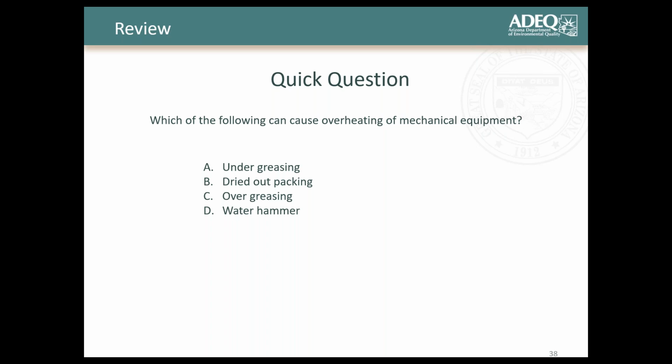Yeah. And this is a great question too, because usually people think undergreasing is a problem, but people forget how bad overgreasing is, and the reason this is the typical answer in an operator exam is because, yeah, undergreasing, of course, for those of you that are fairly mechanical, everybody knows the hazard of undergreasing, right? But usually you're definitely going to get heat because of friction, but you're going to get damage based on wear, right? I think when it comes to operator exams, we definitely want everybody to start.